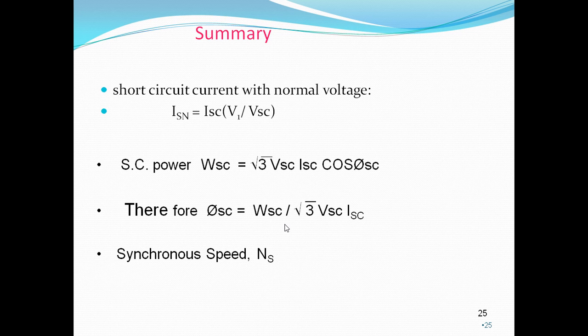To draw the circle diagram, we require the short circuit test and no load test. From the no load test, we can calculate friction and windage losses, core losses in the stator, and the copper losses in the stator.